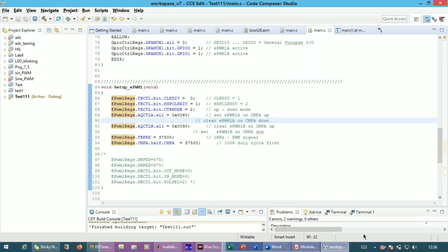So to continue with the previous slide, we will come to Code Composer Studio. Here you can see we have to add an additional line of code to the same PWM which we generated a few minutes back. So here we need some code to generate the deadband units.